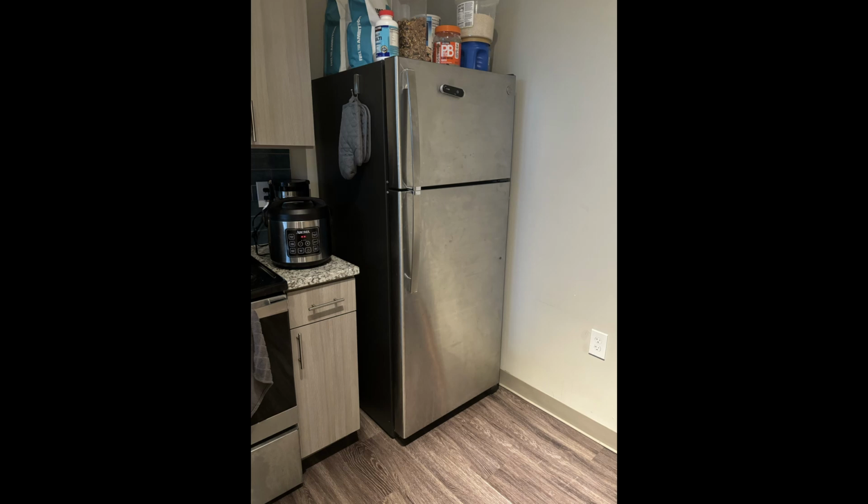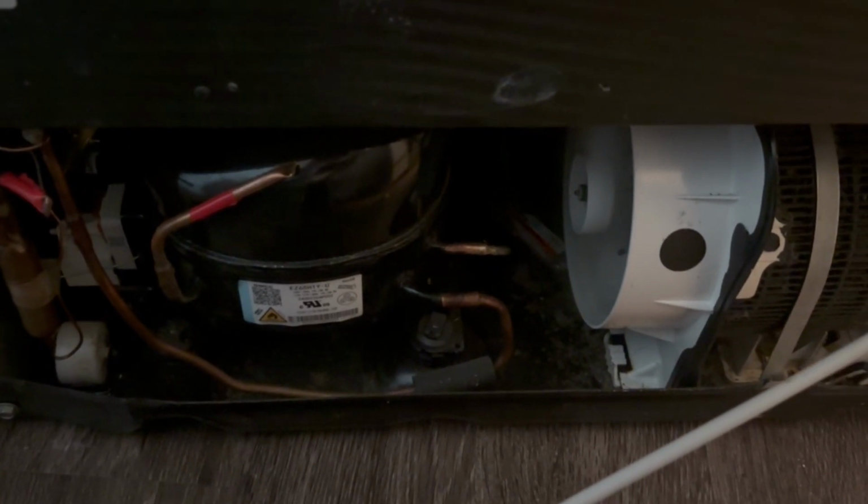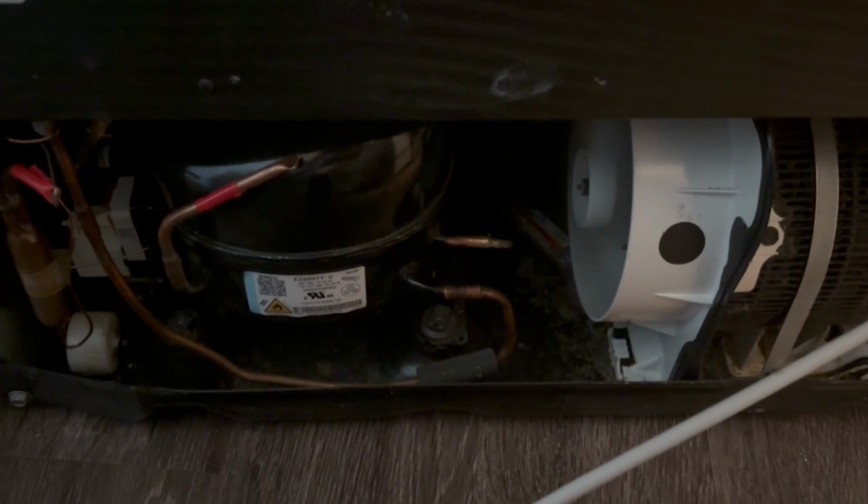The fan motor bearing is bad, and I want to see how much this, along with age, affects the coefficient of performance. My suspicion is that because the fan is not pulling as much heat away from the condenser coil, this will lead to a reduced efficiency and a reduced cooling capacity.